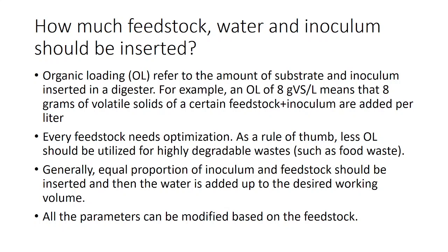If the information about your feedstock is not available online, generally in research articles most of the feedstocks have already been covered. But maybe if you want to use some unique feedstock, or if you want to know actual methane production for your case, the information available online will give you a rough estimation. If you want to do exact estimation of your feedstocks in AD, maybe you can do some experiments at different organic loadings such as 8, 12, up to 20 for less degradable, and for highly degradable up to 4 or 6 gram volatile solids per liter.